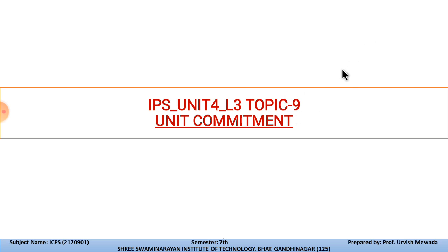In lecture number 2, we discussed topic number 6, that is penalty factor, which is related to the length of the transmission and distribution from the generating station to the consumers. As the line losses increase, the penalty factor of the respective generating station will increase. We discussed this with detailed derivation, and then we discussed the derivation of the transmission loss formula using Kron's method, in which we covered 3 cases and derived the detailed equation for the power loss of the generating stations.